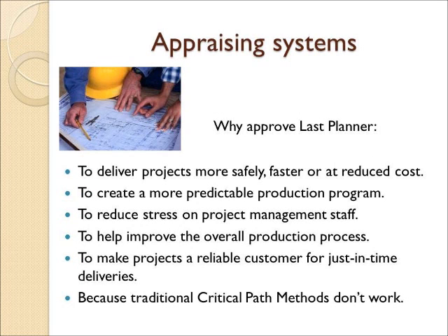I would like to present the Last Planner System as a good method to improve the construction process and to reduce waste. The reasons why the Last Planner is approved are that it can deliver projects more safely, faster, or at reduced cost. It can create a more predictable production program. It can reduce stress on project management staff. It can help improve the overall production process and make projects a reliable customer for just-in-time deliveries, because the traditional critical path method doesn't work.